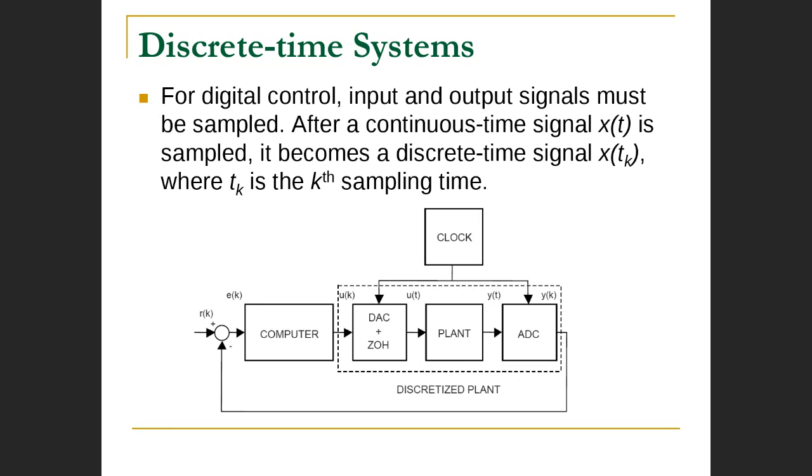Okay. Now, when the computer needs to recognize what is happening to our motor, it needs to use a special device called an ADC to convert this analog signal back into some digital format. So what am I focusing our attention on here? The signals are discrete. Look at this clock here. This clock will take the samples of signals coming from your computer as well as signals going to the computer. It's discrete, right? All right, so this is demonstrating the nature of digital control systems.